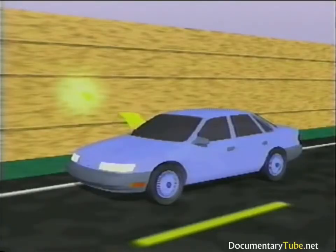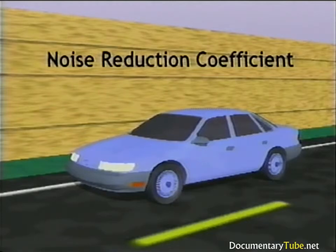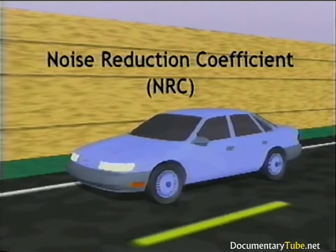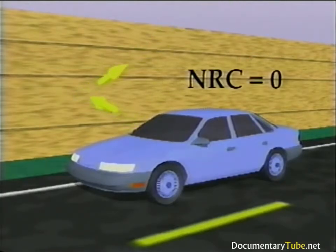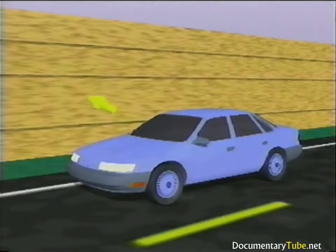The remaining noise is either absorbed by the noise barrier material or reflected. The ability of a barrier surface to absorb incident sound energy is characterized by its noise reduction coefficient, abbreviated NRC. Noise reduction coefficient values are based on an average of absorption coefficients at individual frequencies and theoretically range from 0 to 1. 0 indicating that the surface is totally reflective, or that there's no absorption, and 1 indicating that the material is totally absorptive. NRC values for an absorptive barrier generally range from 0.6 to 0.9.